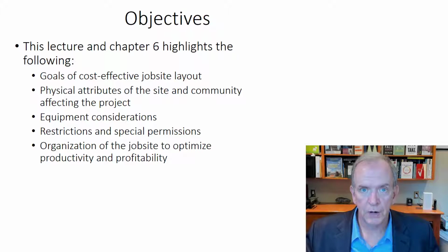As you recall, we looked at productivity rates in the last lecture, and we'll be talking about what kind of space we have in this physical location, and how we plot things on a site plan to determine the best avenues for that. Google Maps can come in pretty handy, giving you an aerial view of what's going on in the site, and sometimes just plotting things on a Google map can be helpful, as well as site layout drawings that you can coordinate with different phases of the work at different time periods.